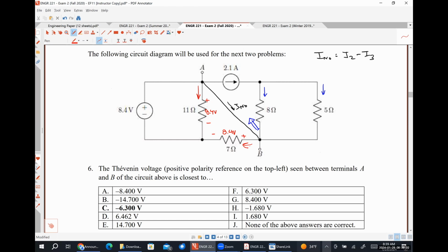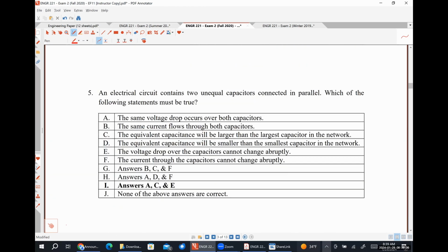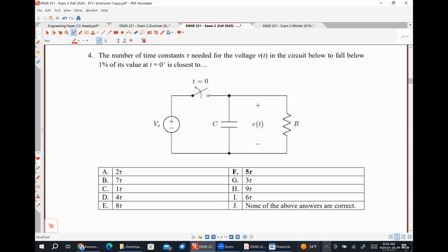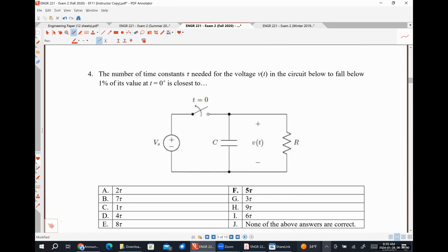Yes, ma'am. So, but you don't even need a table. If you have a calculator in front of you, you can develop it, because it's literally in one time constant, it's going to look like e to the minus 1, which is 36 and some change percent.